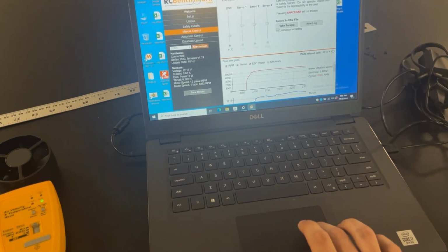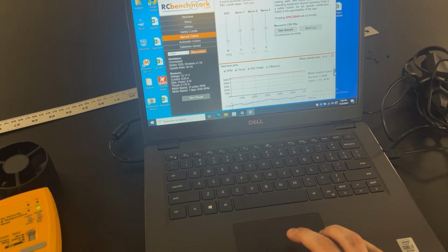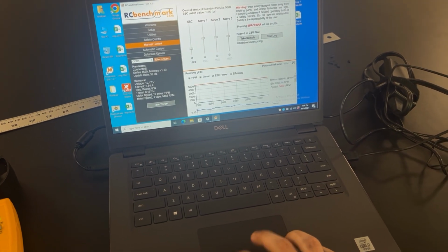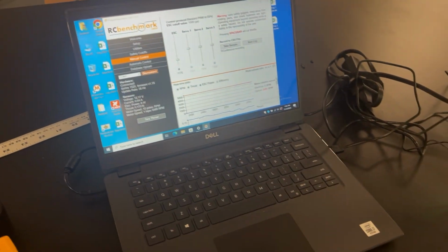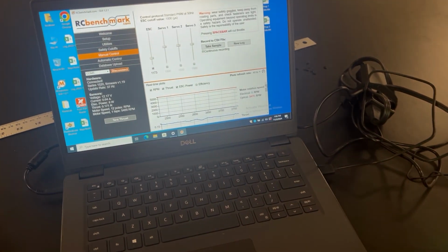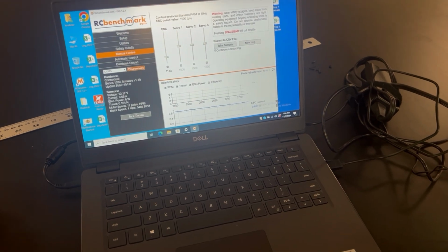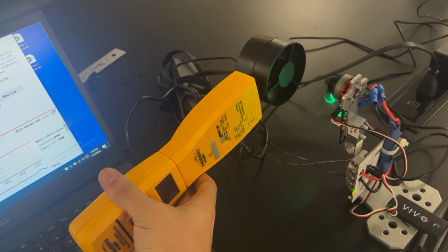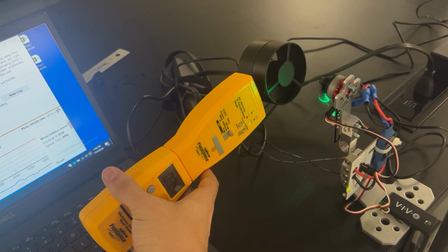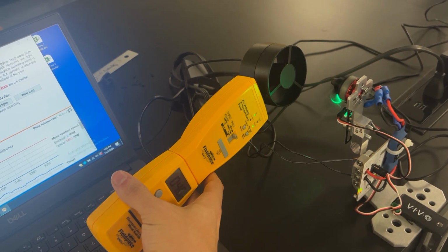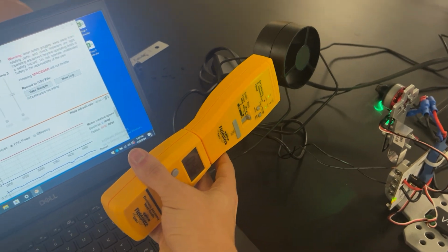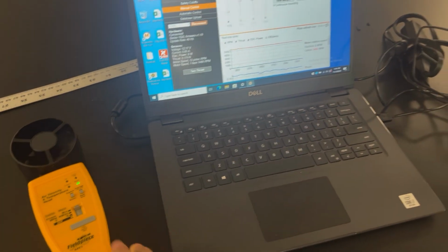In addition, you're going to see that these graphs are now giving some data. RPM, thrust, power, everything. So at each different ESC voltage that you choose, you're going to be measuring these RPMs, thrust, power, voltage, and current, as well as holding this out in front, letting it spin up. And you can see that meters per second increasing to about 4.7 right now. You can get that data.